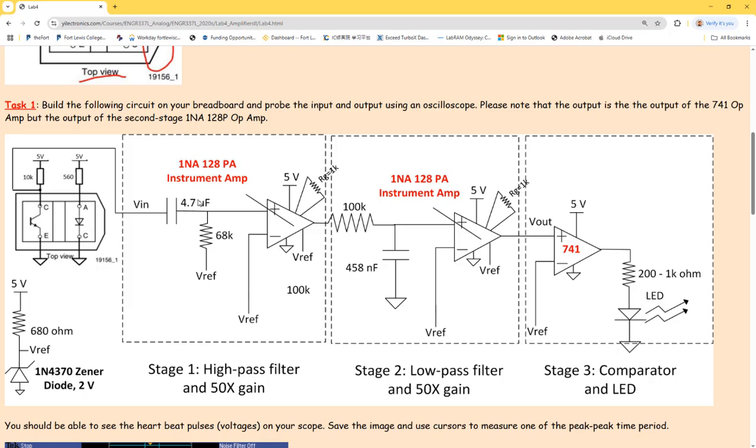So through building this amplifier, you learn how to calculate the cutoff frequency, high pass, because heart rate is usually, for example, 50 hertz to 180 hertz probably. It's the normal range. And you can set up the range from like 30 hertz to 200 something as the signal's frequency. And there's a frequency from the power supply, from the plug, which is 60 hertz. It's really annoying.